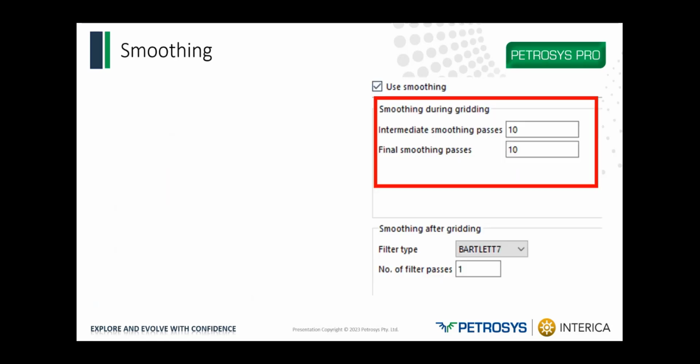I'm also going to talk a little bit today about smoothing. Smoothing can be done in Petrosys locally inside our Spatial Editor tool, and I'll demonstrate that in a bit, or in batch via our surface modeling application. And when I say batch smoothing, I mean we're taking the whole grid and we're applying a single smoothing algorithm across that entire grid. Whereas local smoothing, we're more looking at minute changes within maybe individual contours or individual areas in that greater region.